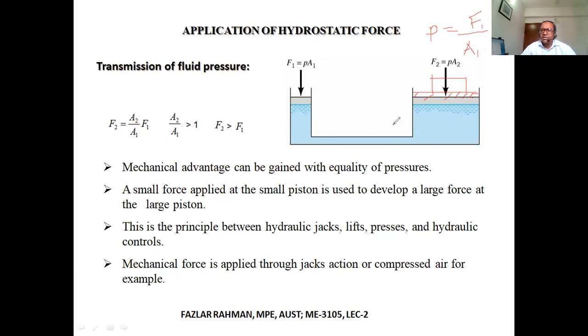Similarly, the pressure inside the fluid is the same. So right over here, we can say P equal to F2 divided by A2. Now this P is the same on both sides. So I can write down F1 by A1 equal to F2 by A2.